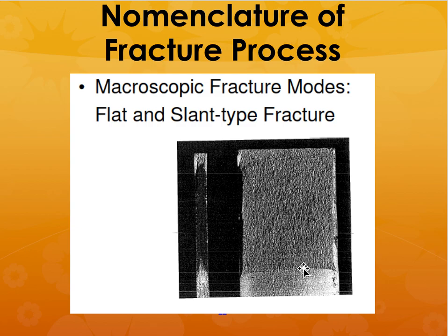Okay, so most of the time, if you have had a lot of plastic deformation, you will see that there are a lot of failure marks present on the cross-sectional area where the fracture marks are present. But suppose there is hardly any deformation at all, you will find that this area is kind of bright and shiny. If it is bright and shiny, that means that the failure is brittle.